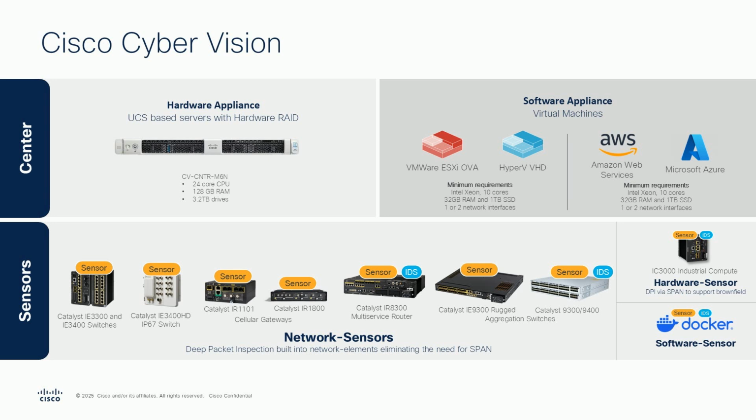In addition to that, Cybervision offers deploying its sensor as a Docker-based application to any industrial compute that complies with the technical requirements. Please refer to the tutorial video for installing the Docker-based sensor. Active Discovery is one mode of operation of the sensor to acquire characteristics of devices. In comparison to the standard of passive deep packet inspection, Active Discovery is based on requests being sent from the sensor to a device in a proactive manner.